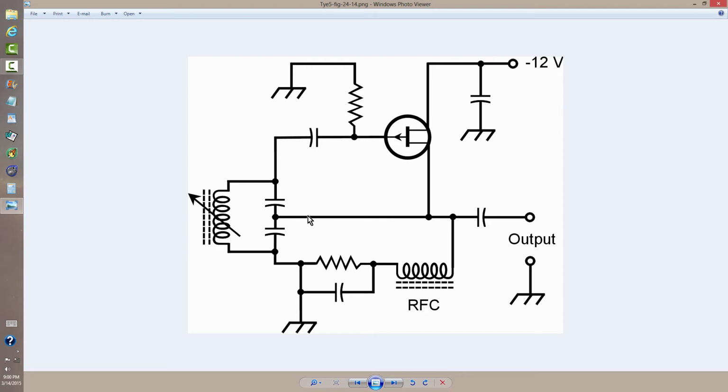The third type of circuit I'd like to show you is called a Colpitts oscillator. It's basically the same as the Hartley oscillator circuit. In this particular example, we use a P-channel junction field effect transistor. The tank circuit which determines the frequency is here, and you can recognize the Colpitts configuration because there is a split capacitor and a tap between them, which goes back to the source, in this case, of the active device. But the split capacitor with a tap between them is the hallmark of the Colpitts oscillator, and the tuning is accomplished by means of this variable inductor.